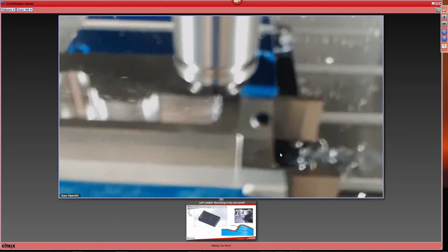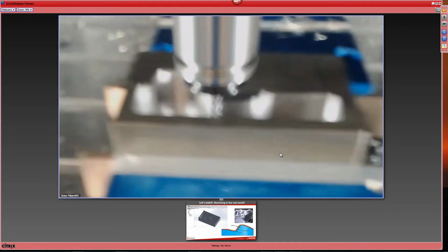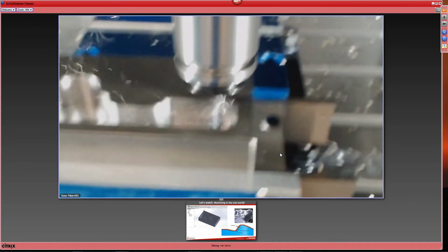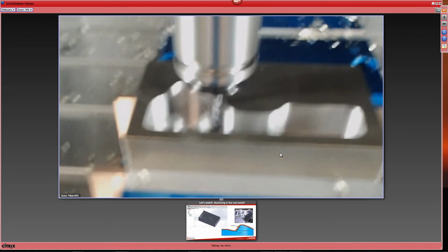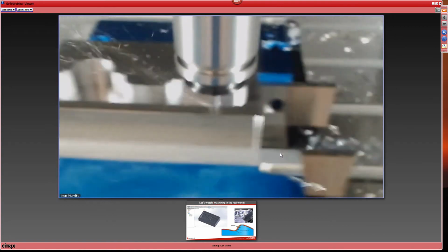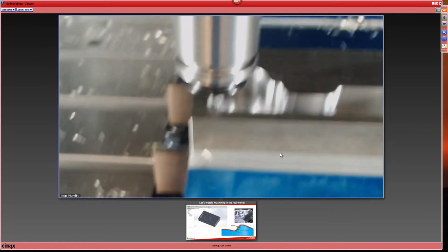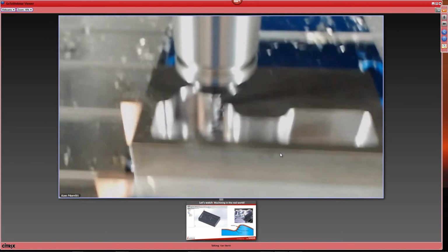Okay? What we're doing is we're keeping it at a G1, and we're utilizing the high feed rate of the machine to reposition that tool so that we don't have that pause going on every time that we're repositioning. And we're minimizing the amount of movement that we're doing by keeping it down in the area that we're cutting instead of always returning to the R-plane.